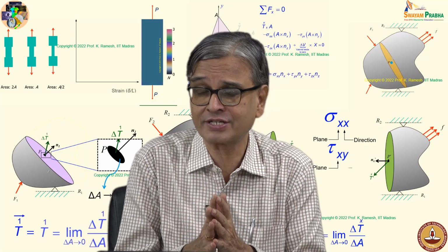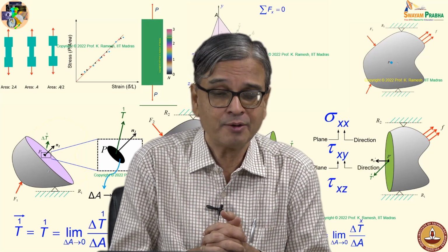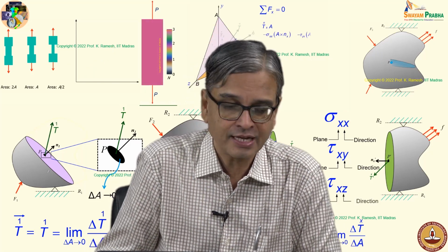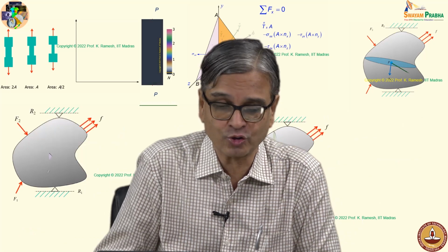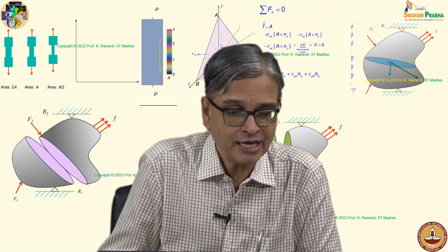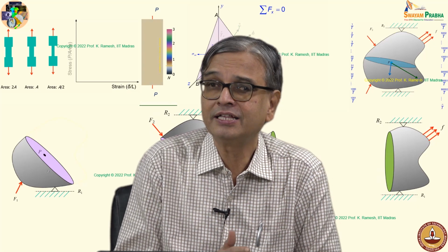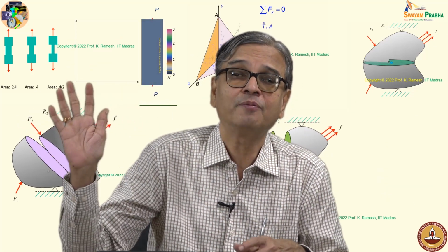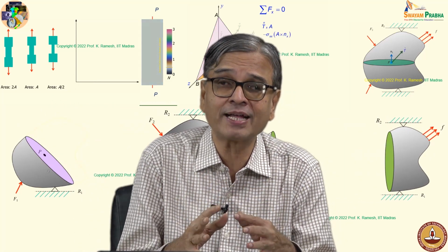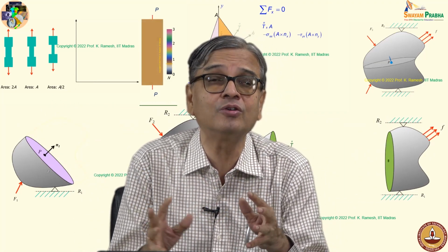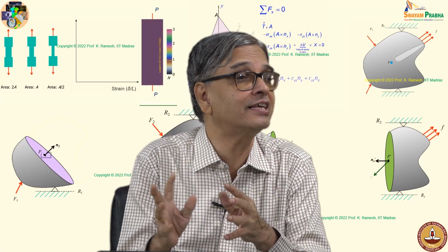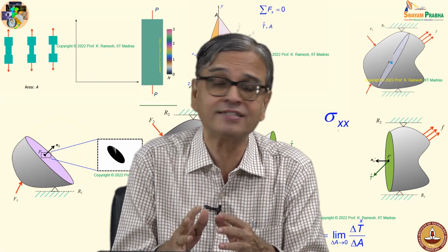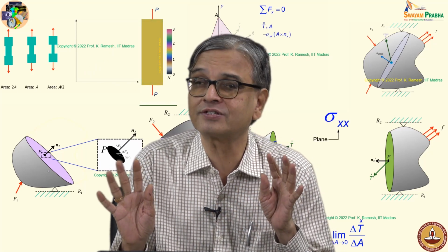None of the books really give you any practical demonstration like what you have from photoelasticity here at this stage of development of the course. So, you have the advantage. I suppose you appreciate the utility of Saint Venant's principle. Many times we will simply say Saint Venant's principle, because with the development of mathematics at this stage, it is too difficult to comprehend what is happening near the load application points. Unless you go to a numerical or experimental analysis, there is no way you can find out the forces.